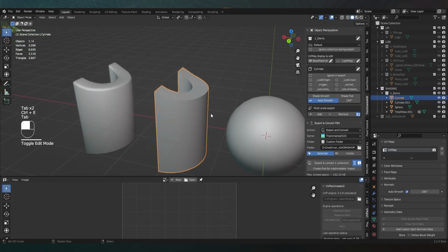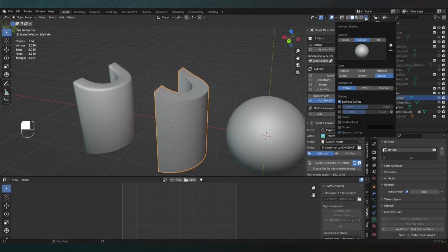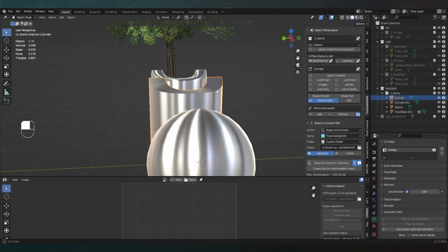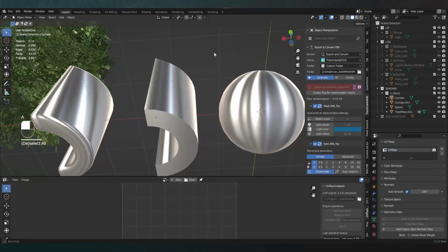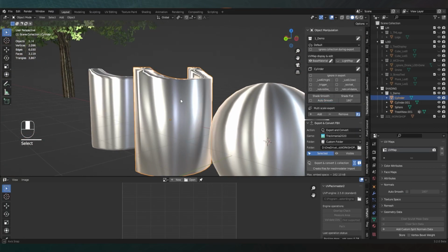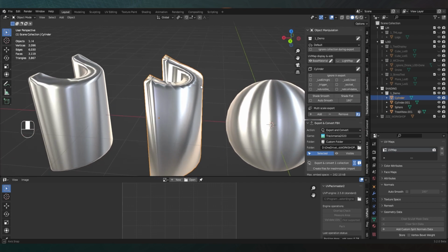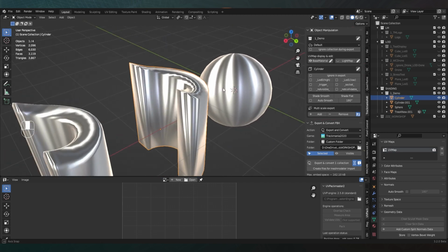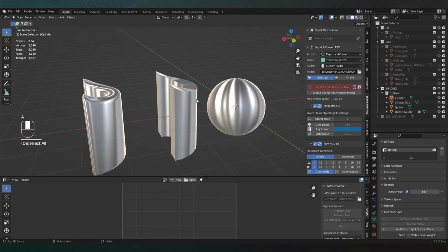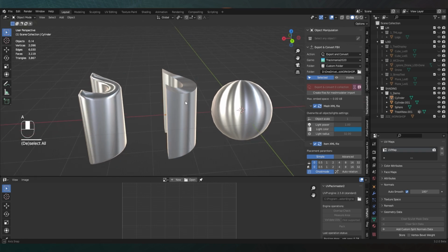One trick actually to properly see your smoothing and to see if a reflection would look correctly, you can go into the matcap mode, which I'm already in, and then select this material, this look, and this really shows you how reflections would look. So if this was not with custom smoothing or auto smoothing, then it would look like this, completely scuffed. So it really helps you see if it's the right smoothing or not.